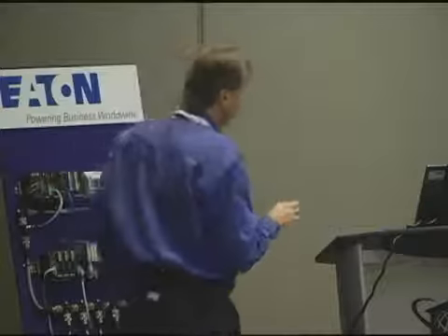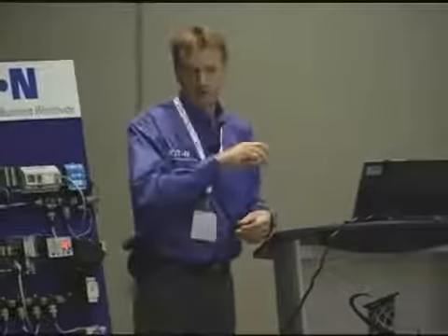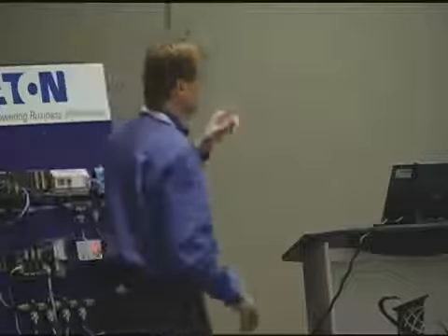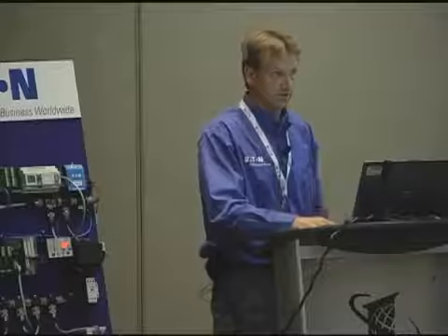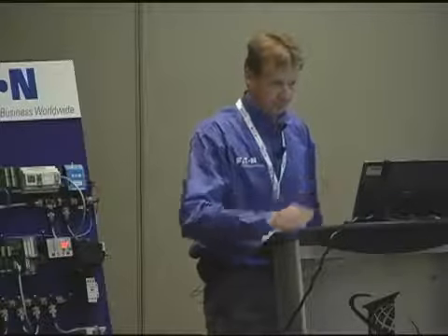Doing this type of topology has very stringent wiring rules. We'll talk about why cabling has issues and stuff. So very stringent rules, but there are industrial protocols that can be developed this way with this topology. DeviceNet is one of these that you could do that as an example.